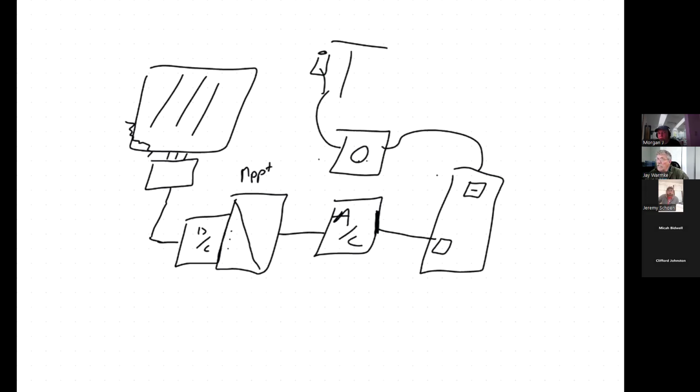But if it's still sunny, it shut off the power, so it's no longer generating AC. But all of the lines going from the array down to the inverter are still live if the sun is shining. You know, that's DC, right? They're still hot and they could be 600 volts. Right. So if I've got a building here, let's say my home is like this and I've got the solar array up on the roof and I've gone through the attic and I've gone outside and I went down into the basement.